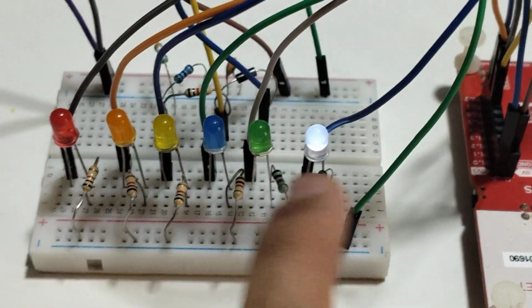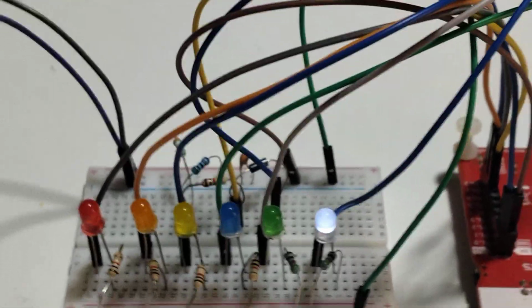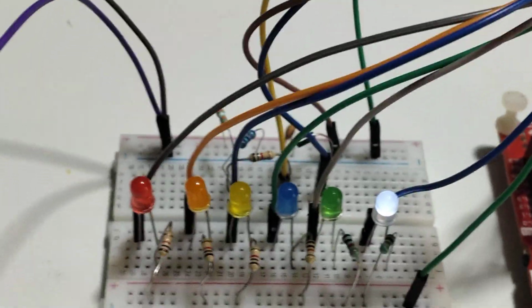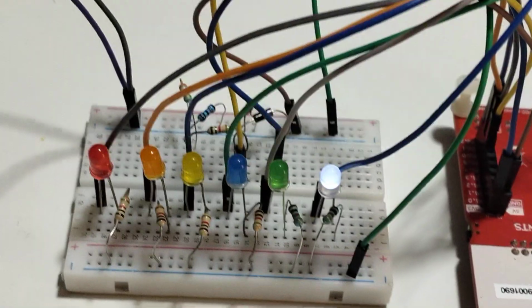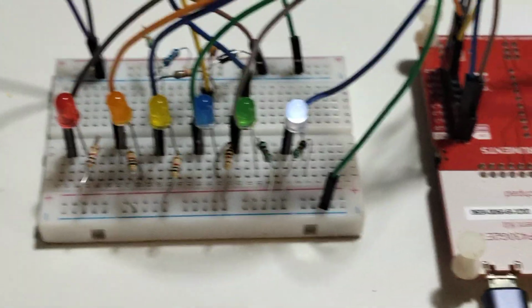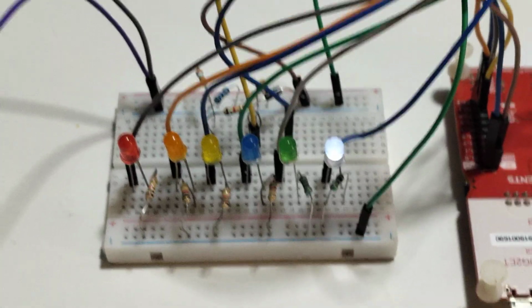And you can see here this white LED is currently lighting, and as I showed you in the code, if it doesn't measure anything, the white one lights. The reason it's not measuring anything is that I haven't connected this yet to the power supply, which is going to supply the 13 volt thing. So right now it's just lighting the default LED, which is white. Now I'll connect the power supply, and you can see immediately that it will jump to green, because we're going to be measuring something like 2 volts. So let me just connect that.